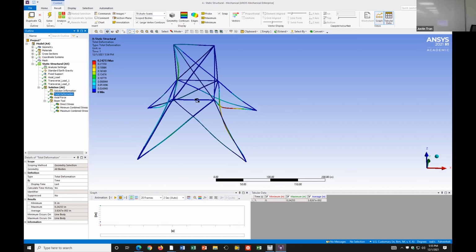Yeah, that's not the same Z. It's still acting perfectly parallel to the actual flat surface of the wall. So the wall's getting pulled that way, so you can only apply axial modes that are perpendicular to that wall. And so the axial mode you have to do separately with the net force. So just do a force thing, and then also select the inner surface of that. At first I thought there's no flat surface for it to push against, but I guess it's just the whole inner tube being pulled off that direction.